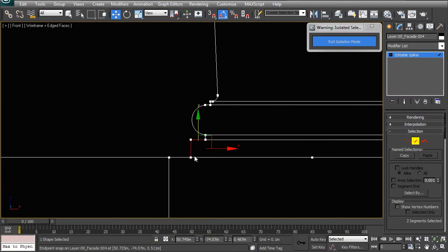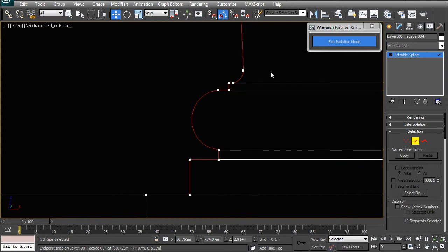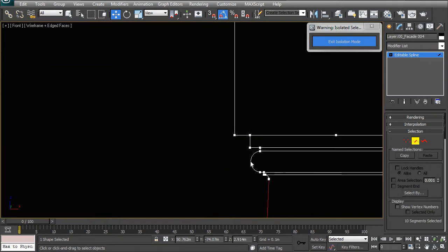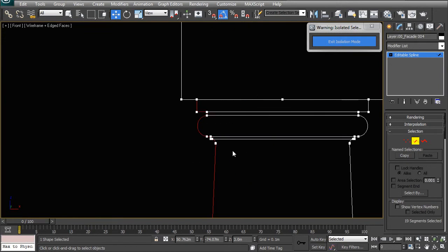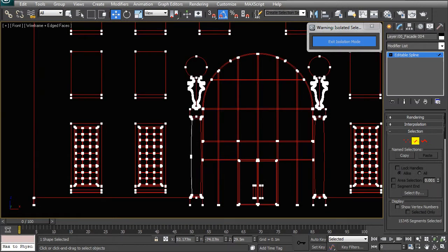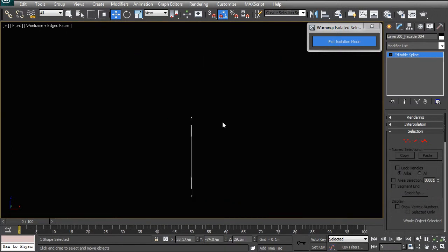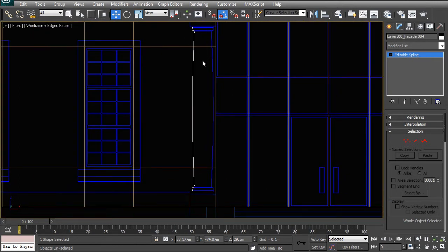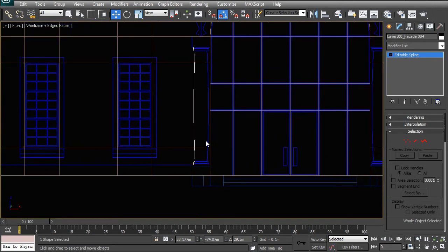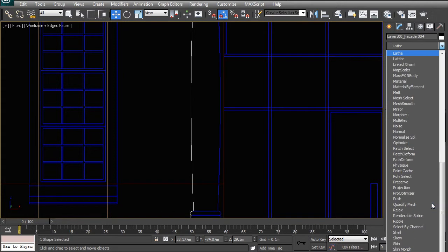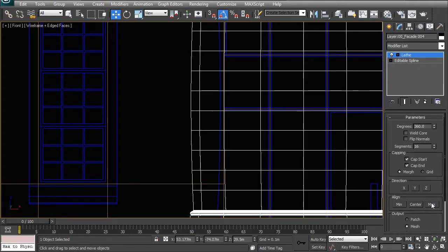So in our case, I'm just going to go and select the outline, which is all of this. And I'm going to do the same thing up here, deselecting those. So then all you need to do is go Control I, hit delete, and then you have your spline, which has now been extracted out of the CAD geometry. Now this spline, you can go and in your modifier just look at lathe, so LA, enter.